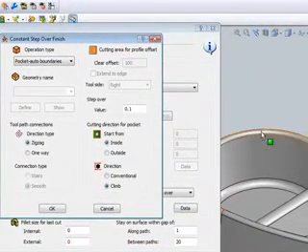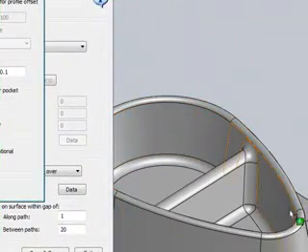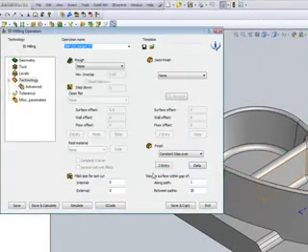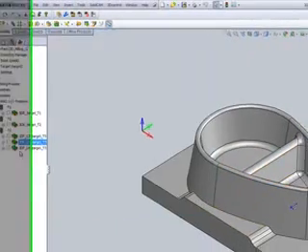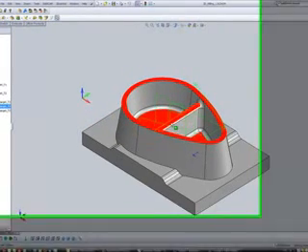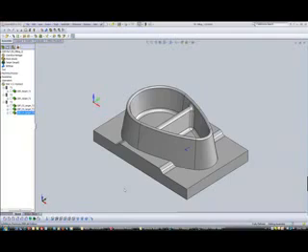In other words, the boundaries will automatically be taken from our working area, which is limited to these areas over here and to this floor. And if we take a look at our toolpath generator over here, you'll see that it has been created on these floors over here, on these radiuses here on top, and this radius around the part itself.